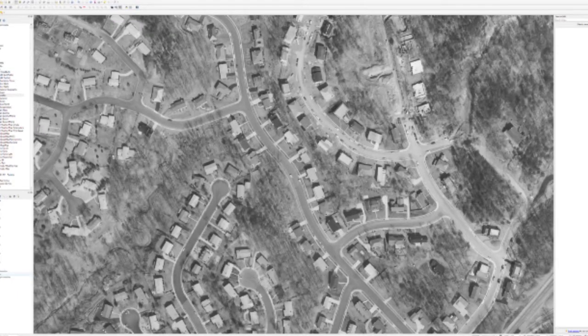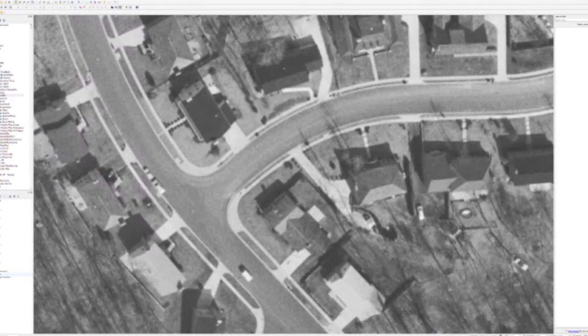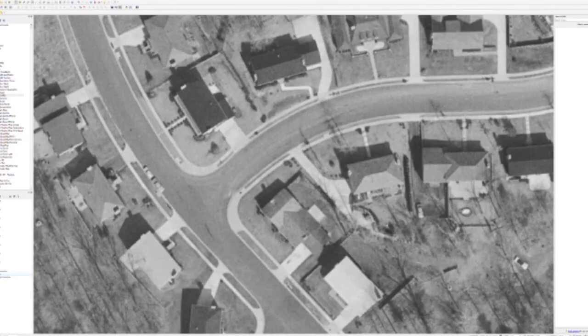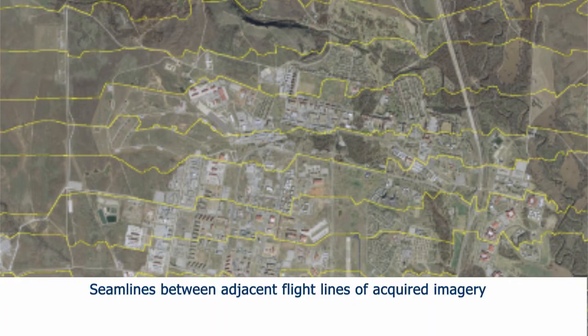In general, orthoimagery is not a true ortho, so rooftops or buildings may lean. In order to make a true ortho, it takes a lot more work, and it takes a much more involved DEM in order to make sure that the rooftops or the buildings do not lean. Manned aircraft sensors introduce fewer seam lines, both with frame-based and push-broom sensors.